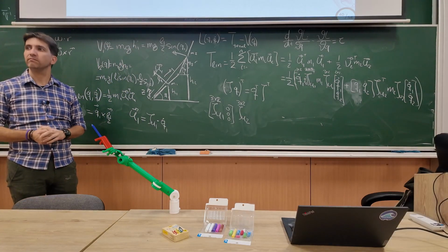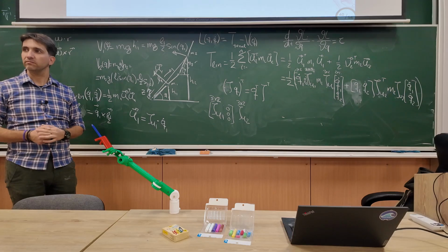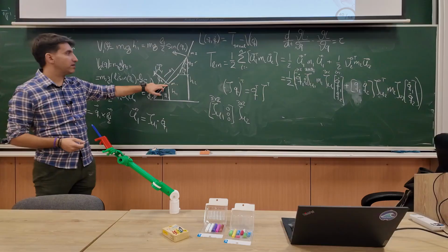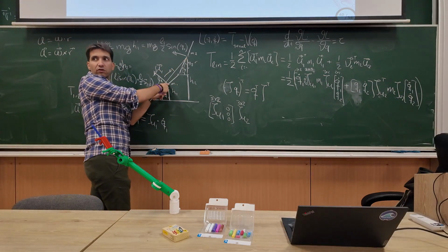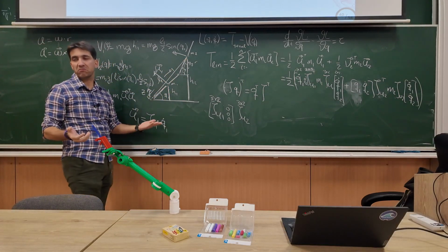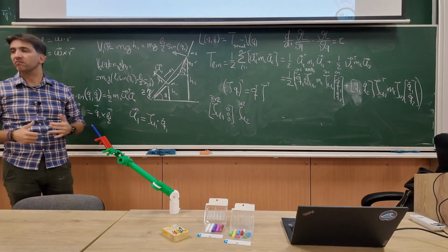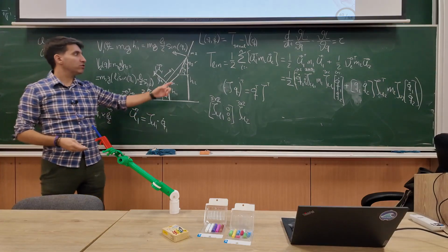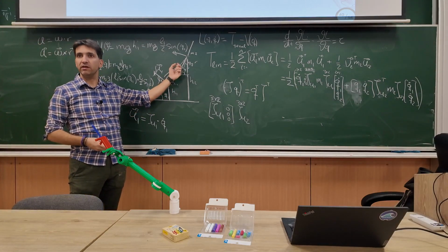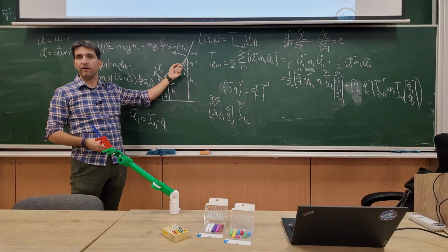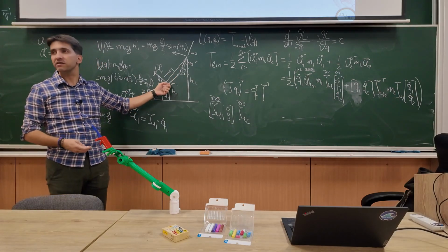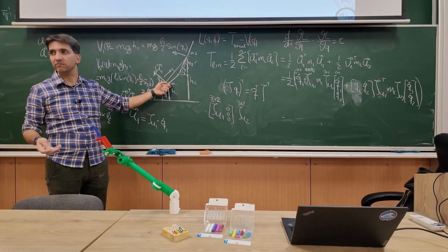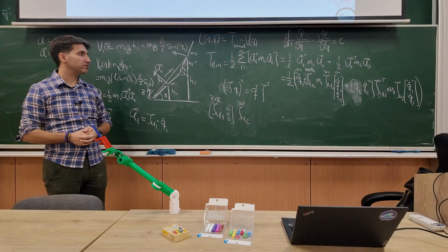Is it from the DAG or a mathematical explanation? There is an explanation that the effect of Q2 on the velocity of mass 1 is 0. You can also see it like this, because that's what the Jacobian tells me: the contribution of this velocity on the end effector velocity, and in this case the end effector is mass 1, the contribution is 0. So I can add it. That's the explanation.